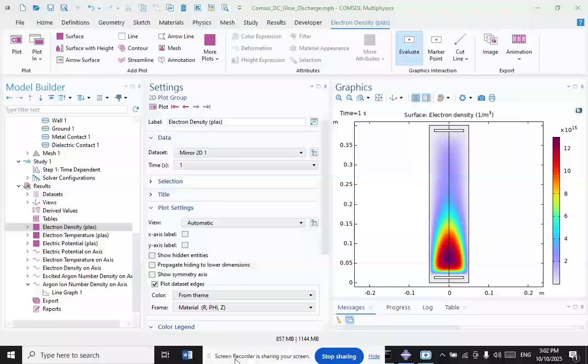The potential, pressure, and the current are interrelated. Only two can be directly controlled at once, while the third must be allowed to vary. The pressure is most typically held constant, but other schemes may be used. The pressure and current may be held constant while potential is allowed to vary. The pressure and voltage may be held constant but the current is allowed to vary. The power, which is the product of voltage and current, may be held constant while the pressure is allowed to vary. Glow discharge may also be operated in radio frequency.